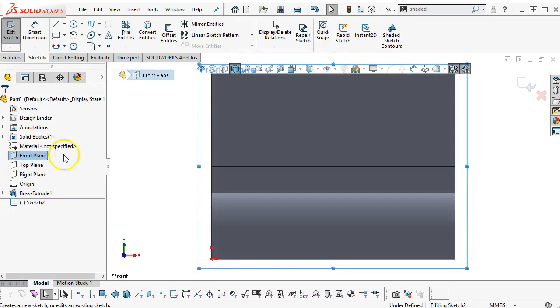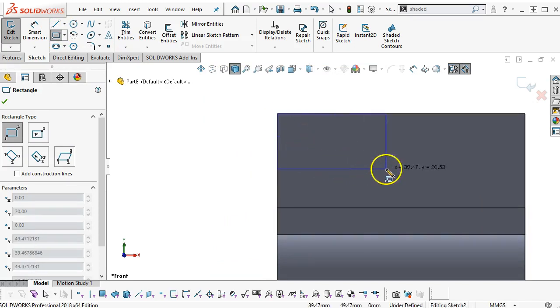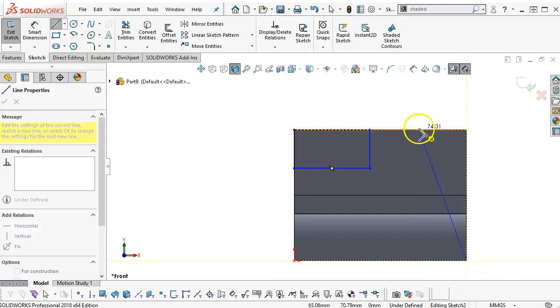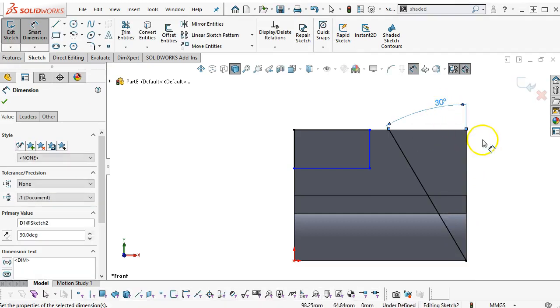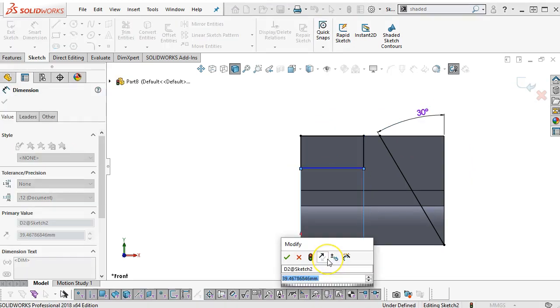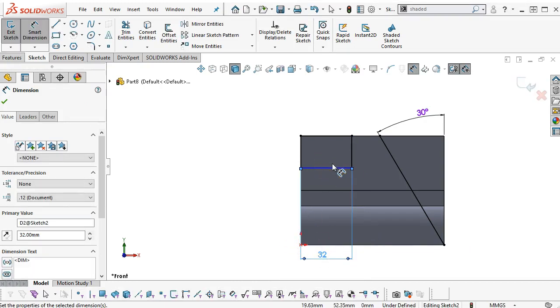Going into the front plane then, we'll generate the two cuts. Well, at least the one cut. Now let's go ahead and generate the two cuts. Alright, so from the bottom edge, up at the angle till it terminates. And then the first thing that jumps out at me is I am trying to mix an open profile and a closed profile, which is not going to be able to complete. It's going to have an error. So 32 millimeters with a depth of 15.